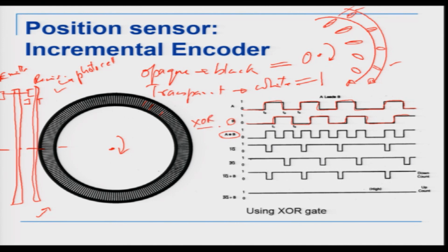Now, XOR gate basically means that if there is any change on any one signal, the output will change. Okay. So, what it does is, if you see here, the signal is going straight. So, this part is straight, there is a change there. So, immediately there is a change here. This is again constant. Then the second signal, there is a change here. At this point, there is a second signal change right here. So, this comes down here, and again it is going straight, again this one comes down. So, there is again an up here. Okay. So, depending on any change here or here, there will be a change on my signal here.